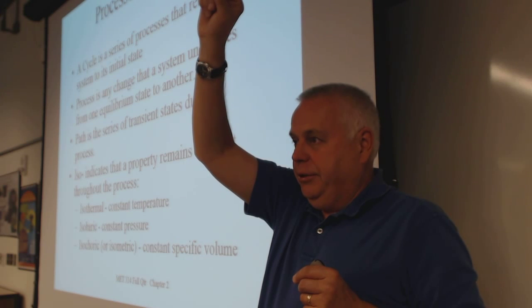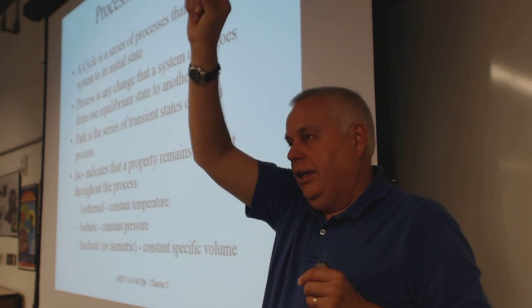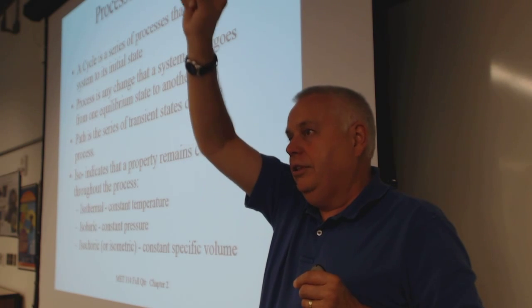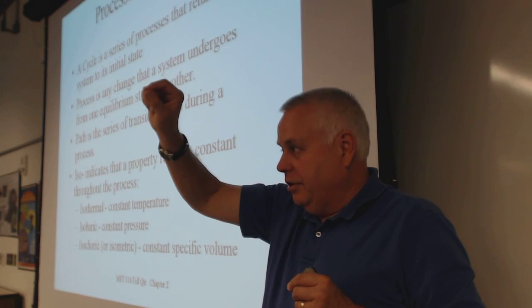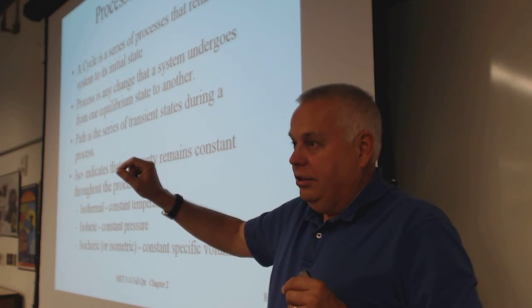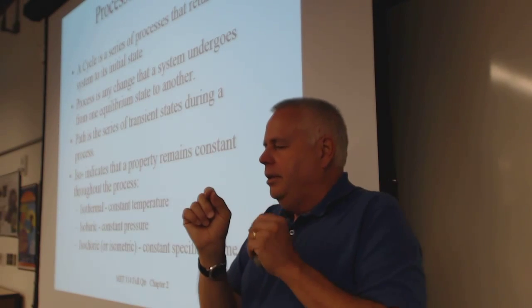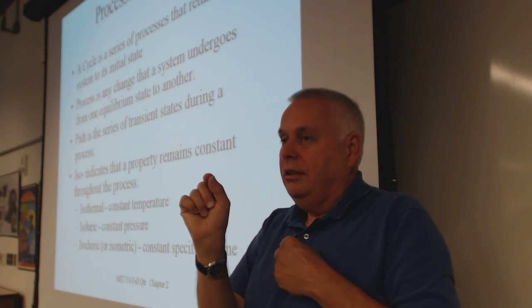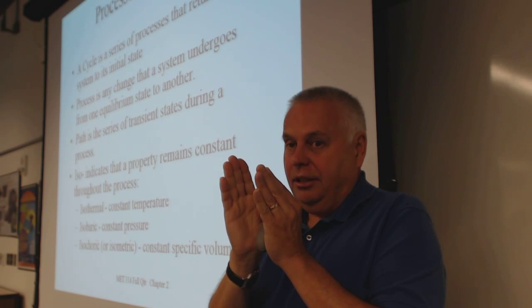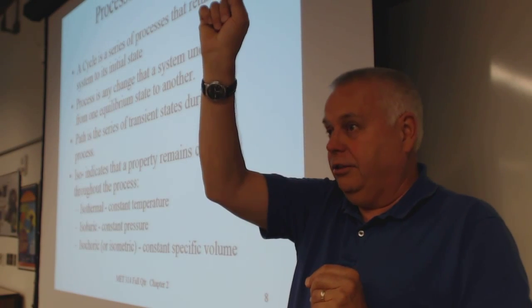And then we light it off, and at the end of combustion, we're going to have a different temperature and a different pressure. Then we're going to have the power stroke, where that increased pressure from the increased temperature from burning the fuel expands as the piston moves. It's pushing on it, and that's another isentropic expansion. The combustion process will be a constant volume process, because the piston goes to the top and we light it off, and the piston's pretty much parked there while it burns.